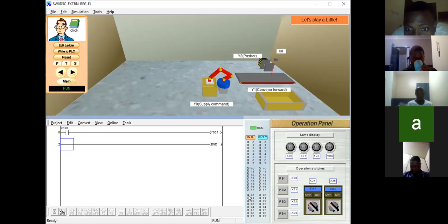This is 20. So when I press this button, I expect this light here to come up. And then the corresponding output, this is your output side here, which is Y, is 1. So I expect this 1 here to come up. So let's press it. Now, can you notice that? See your X20 here coming up as your input. See your Y here coming up as an output. Don't forget, I still press it down, and that is why my conveyor is moving here. You can see this moving. If I release my hand, the conveyor stops moving. That is how a push button works.